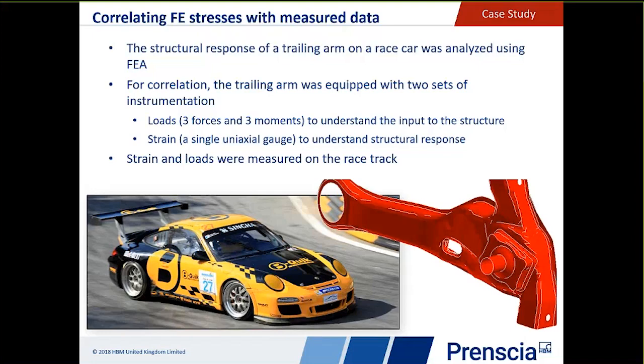We have a structure that we have done an FE analysis on, and we also have a similar structure as a physical test part that we've taken out in the field. This particular one has been instrumented with a load cell. You can think of this load cell as a wheel force transducer, where we've measured X, Y, Z forces as well as X, Y, and Z moments.